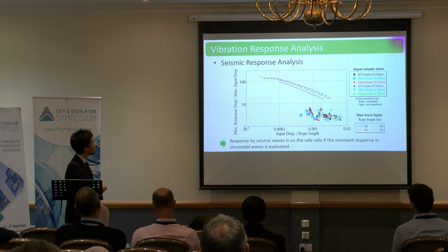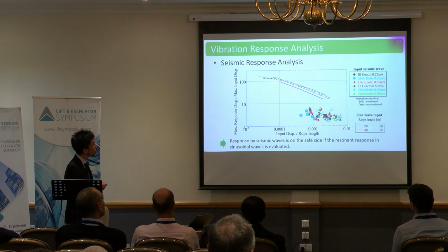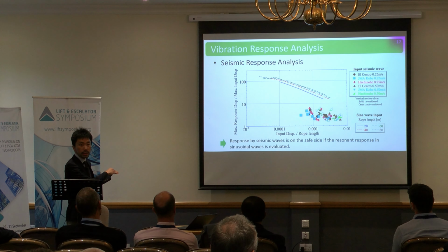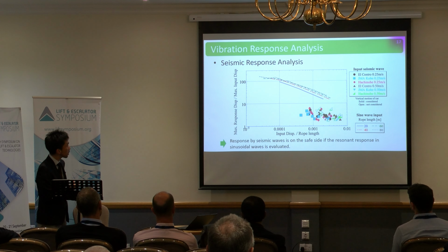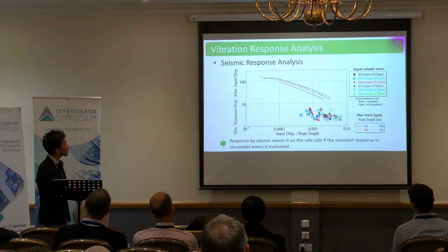And also the seismic response is smaller than the response to the sinusoidal wave. So if the resonance response to the sinusoidal wave is considered, it will be safe for the seismic response.